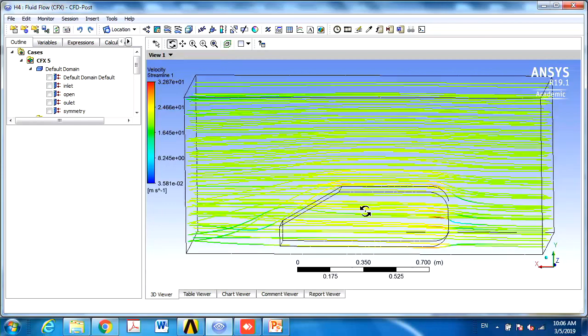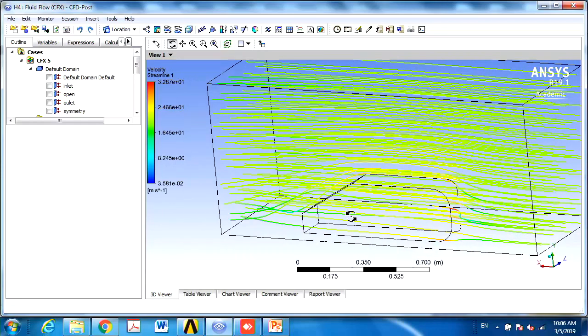Yeah, so you can either tackle this problem in 3D or 2D. Some tutors mentioned to me that 2D is actually not so bad because you can refine the mesh even further. If you do 3D, you need to put more mesh on the depth as well, and your limit is always 500,000, by the way. So you can't go beyond that, unfortunately. But we tested this case already. No matter 3D or 2D, you can get a reasonably good result.